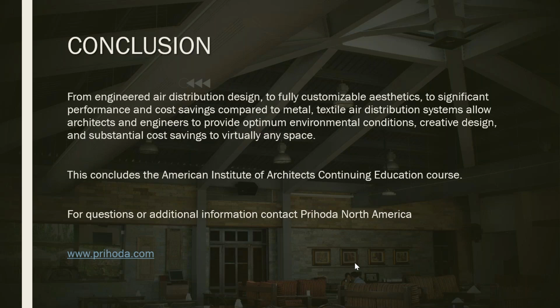So the next question is, how do you do elbows in a fabric duct? Pretty much the same thing as metal. We make the proper radius elbows, 4-gore, 90-degree radius elbows. Even if you're using internal support methods, we put the internal support method inside of the elbow, so it keeps the same continuous look. You won't just have the diffuser that's internally supported and then the elbows are draping. Even with the internal supports, it goes all the way through every single fitting. Even if you have T's or Y's, the internal support method goes in those.